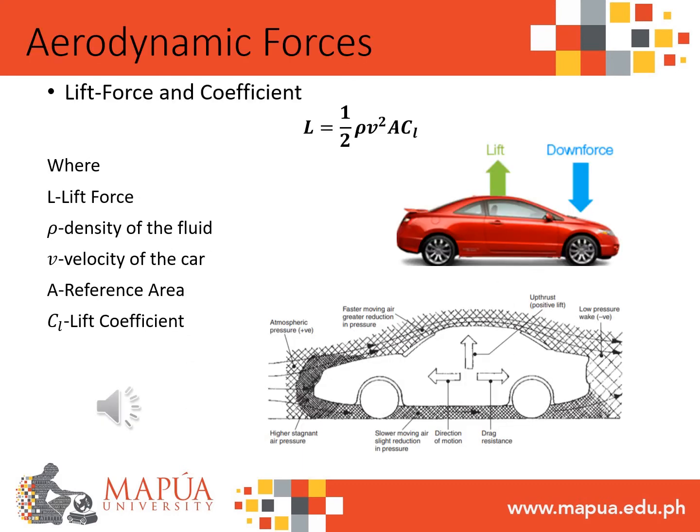Moving on, I will now be discussing the aerodynamic forces. First is the lift force and lift force coefficient. In aerodynamics, lift is a force that holds and opposes the weight of a flying object in air. Lift force is a vector quantity, meaning that it has a magnitude and direction associated with it. When a lift is generated, it acts upon the center of pressure of the object and is induced perpendicular to the direction of the flow.